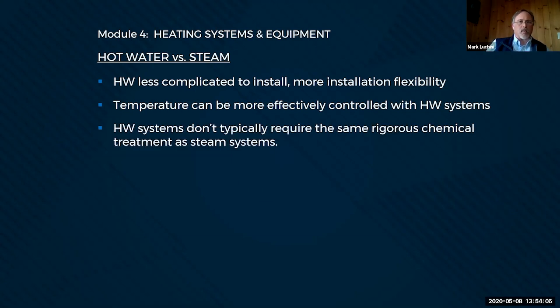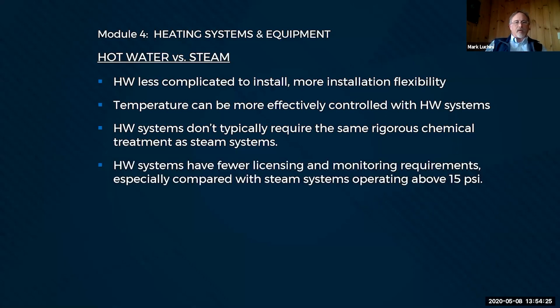We don't typically require the same kind of rigorous chemical treatment in a hot water system as we do in a steam system. That's not to say that we don't treat hot water systems, but you don't have to pay quite as much attention as you would with a steam system. Hot water systems definitely have fewer licensing requirements. If I'm running a steam boiler above 15 psi, I have to have somebody on staff, basically on site, while that boiler is running. Okay.